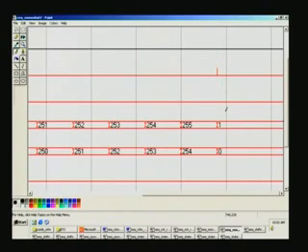But you said momentarily it's 255, right? Yes. Momentarily. Is it not supposed to be reflected there? Here. So it is so fast it is happening, right? Because the moment it goes to 255, perhaps, let us examine after back annotation. Let us see whether that shows up. You are right. That's a point we can examine later on, right? Right now we can't because the simulator does not contribute to the gate delays. That's why I said instead of 50 megahertz, which is shown here, suppose I make it 2 gigahertz or even more. This will still show up, and unfortunately many people have jumped to conclusions based on mere simulation.